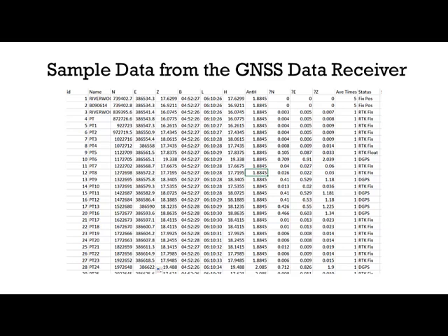So once these points have been gotten, these coordinates and elevation, for a topographic survey, these coordinates and elevation will then be imputed into a CAD software. This CAD software will then generate a 3D view of the surface. So it's going to show you undulations of that surface.